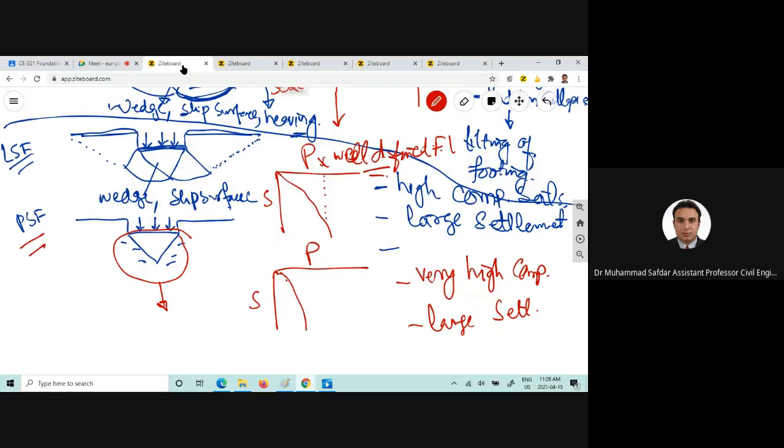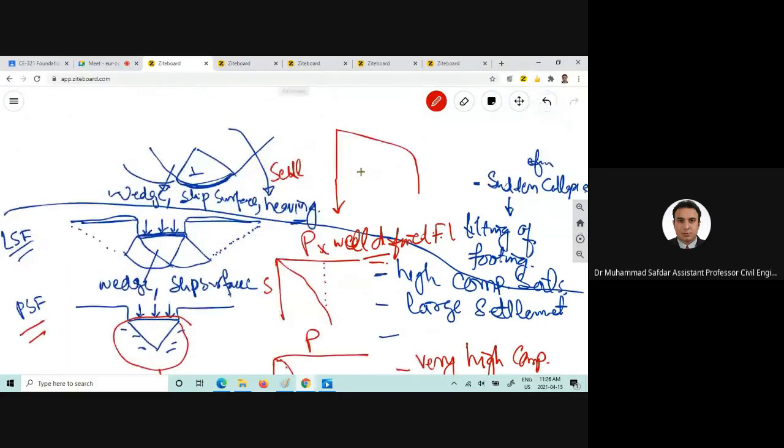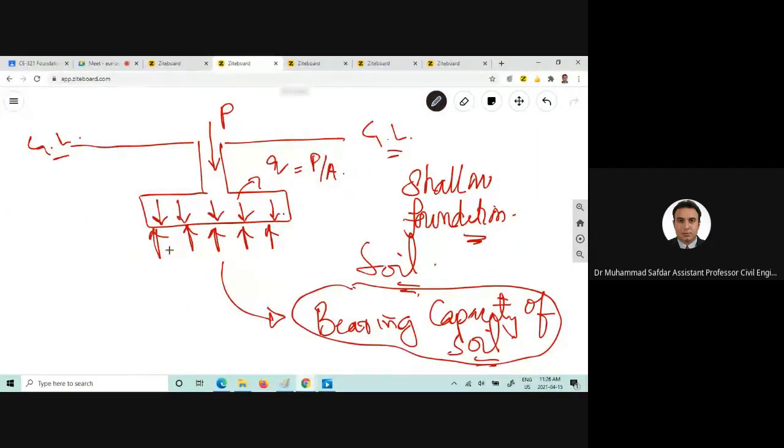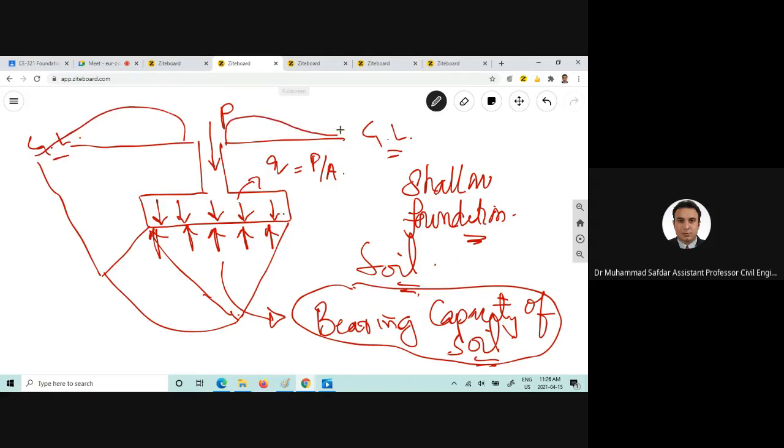Okay. That makes sense. No problem at all. Now these are the different types of zones which are created beneath the foundation. For example, there are different theories about how this soil is going to behave, how the failure mode will occur, and how the soil will heave when the load is applied. So there are people who are talking about the different failure modes, and as I told you, we will discuss that in great detail in Terzaghi's bearing capacity equations when we are deriving it.